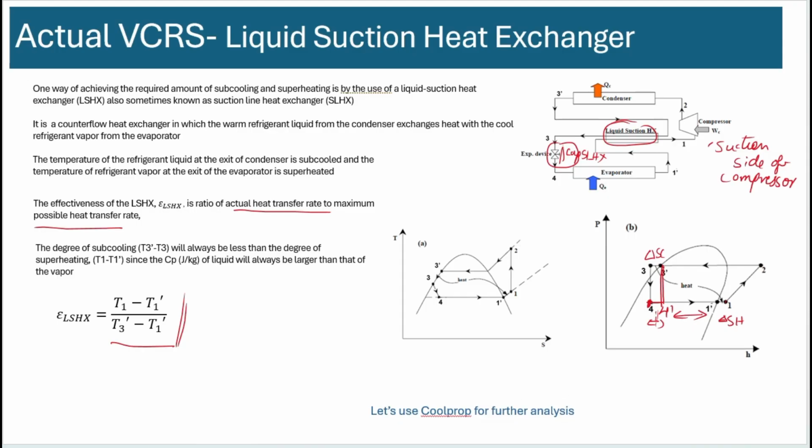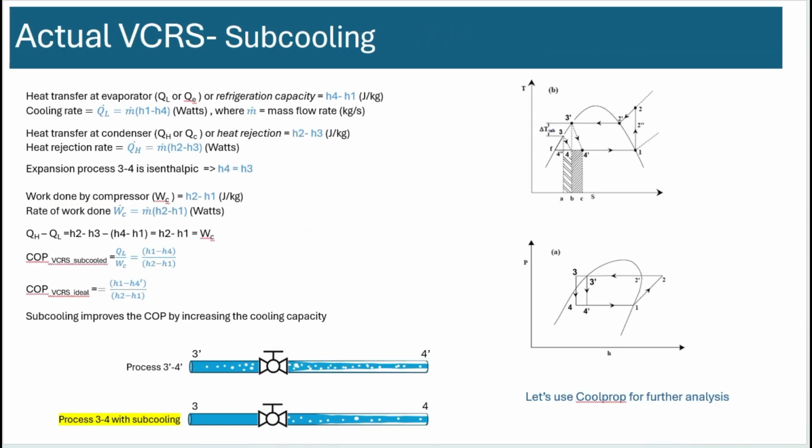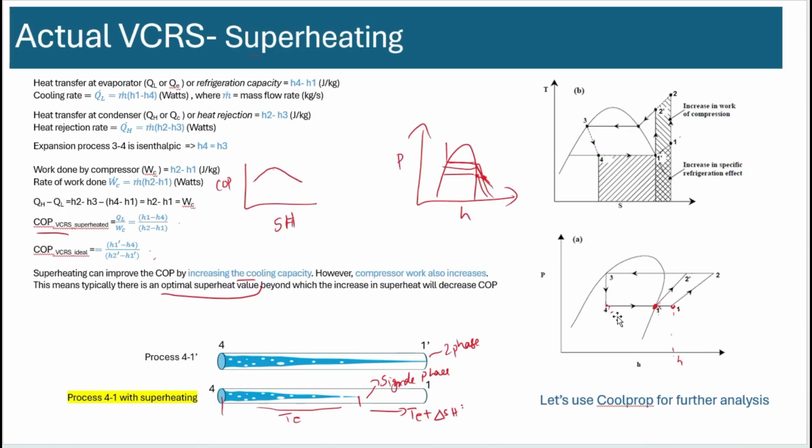Okay, all right. So that concludes this lecture on vapor compression cycles. We had looked at the ideal and actual vapor compression cycle to a certain extent. We are primarily analyzing them using the two-phase diagrams, but you can actually calculate the wattage by using a mass flow rate. If you know the mass flow rate, you can multiply that with any of these numbers like QH, QL, or W to calculate the actual capacities and the actual work done in a real system. All right, thank you.